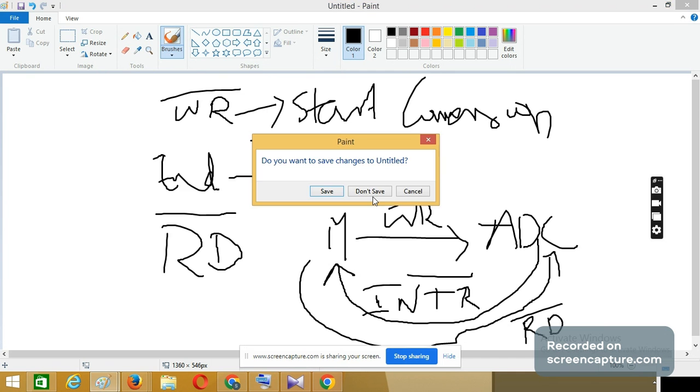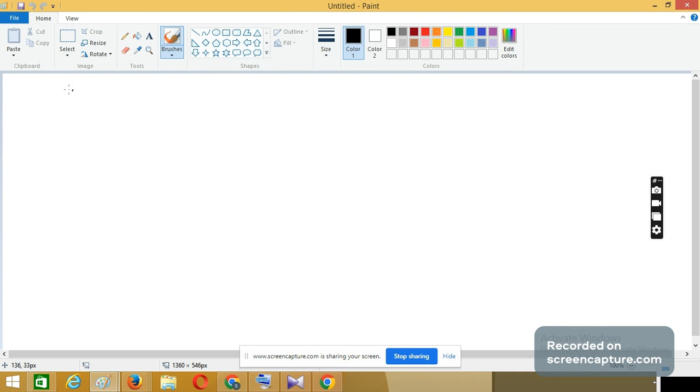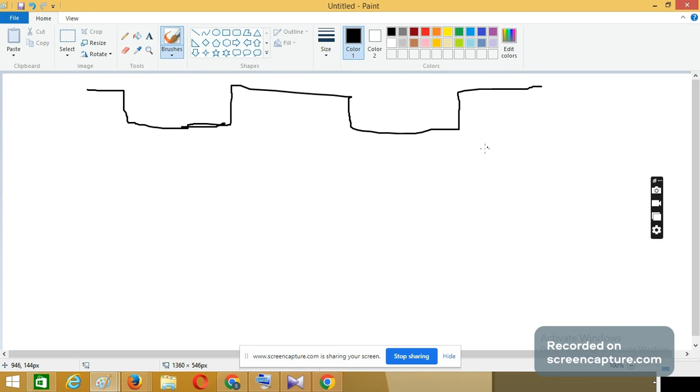Very, very important: how the control signals behave. According to that, you have to write the program. So there will be a CS, a clock type of signal, which can also be permanently grounded. So this is the chip select. Now whenever CS bar has happened, CS bar means 0, active low, the microcontroller has to give information to start the conversion. So it is somewhere here. When CS bar is down, it should happen.